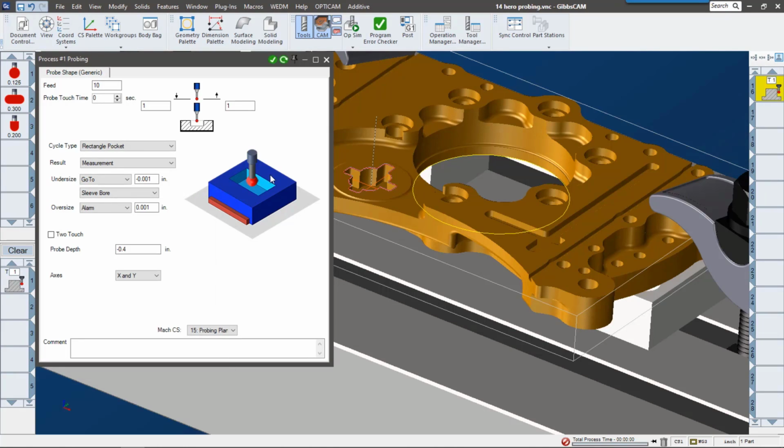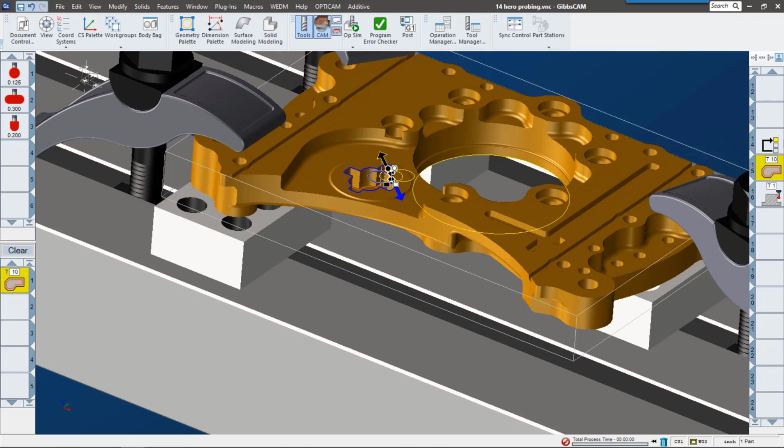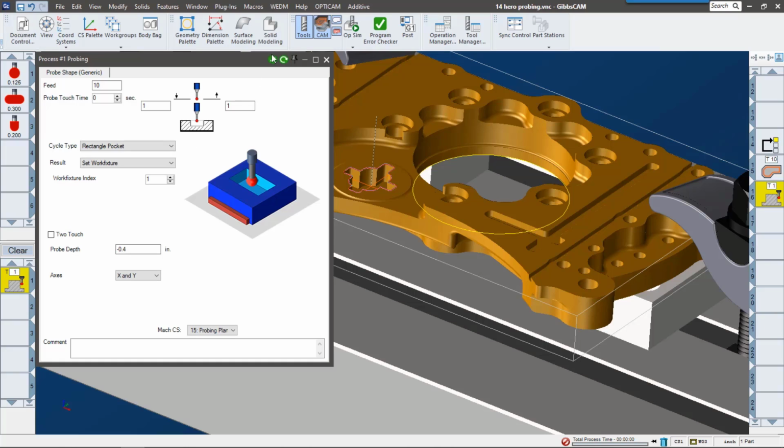And what these are is they're targets. I've kind of pre-baked this a little bit. If we look over on the right, you can see I have a GoTo move, and then there's my contour. So I'm going to say go to the sleeve bore. Again, here's my target, and then run the program from there. Let's go ahead and check this out in simulation.